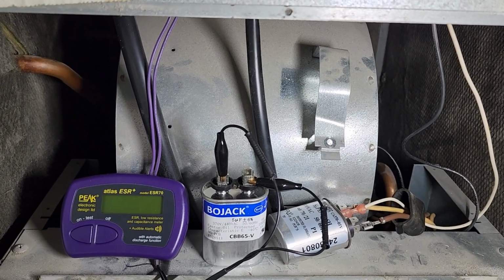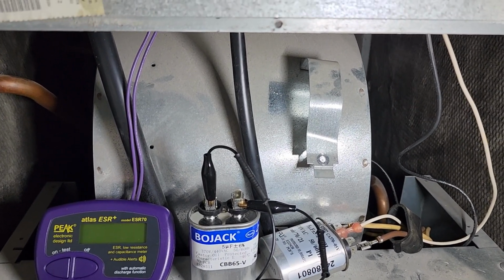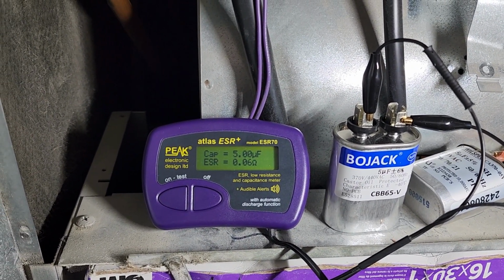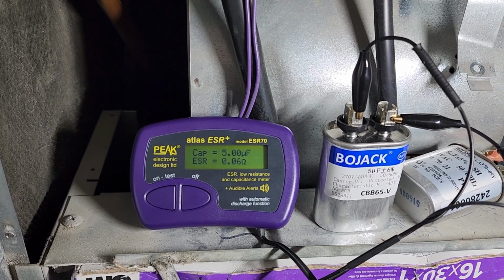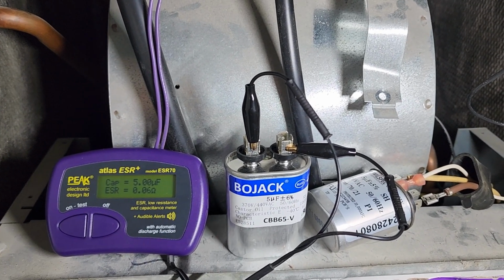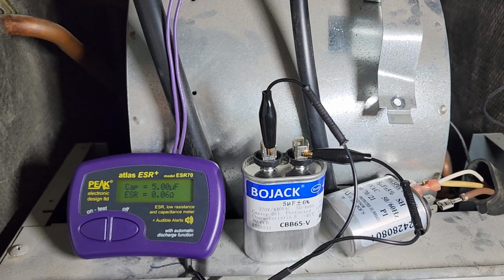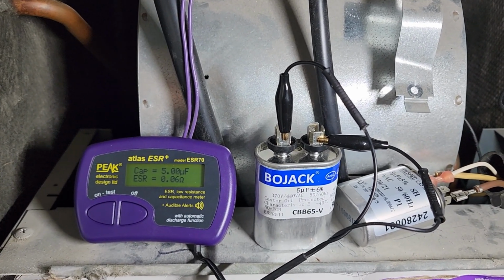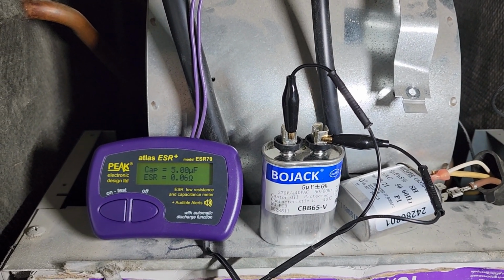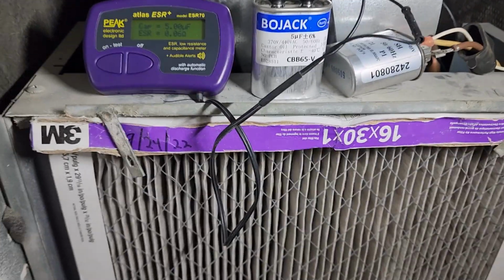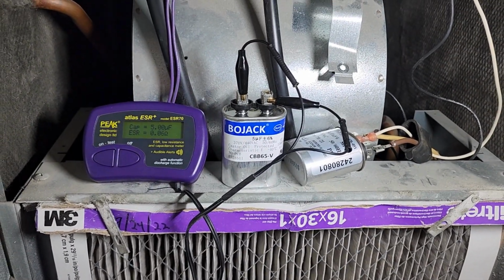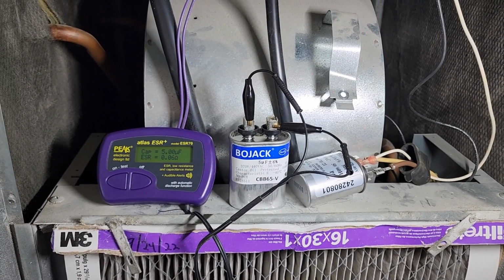Alright, so we have our new capacitor, and let's just make sure. We will find out together how this one looks. Oh, look at that. That is absolute perfection. So we are going to put this back. Of course, there is a tiny minuscule chance that the blower is also bad, but I have a feeling that it is absolutely fine, and it was just the capacitor. So put that back, we'll test everything, and I changed this filter about a year ago. It's actually way overdue, so if the blower works again, I'm just going to change out that filter.